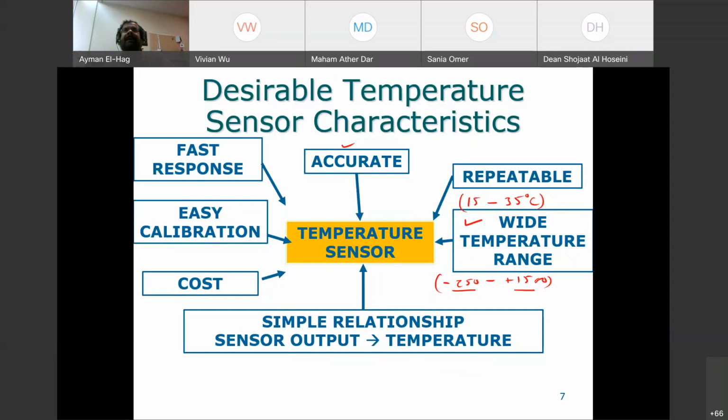You are measuring something at a very, very high temperature. So if the temperature is, let's say, 560 or 562 or 540, it doesn't really make a difference if there is error in that range, even in full degrees. So it depends on the process that you want to measure. What is the accuracy level you want to see? You will select your sensor.